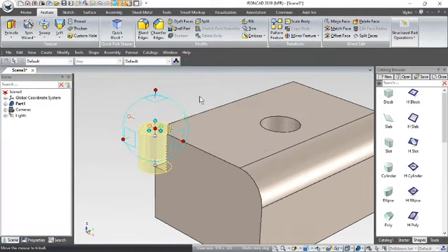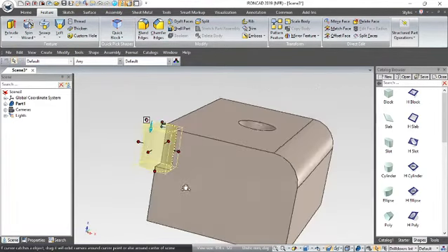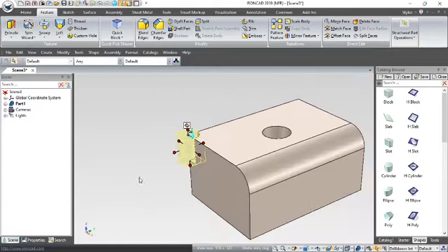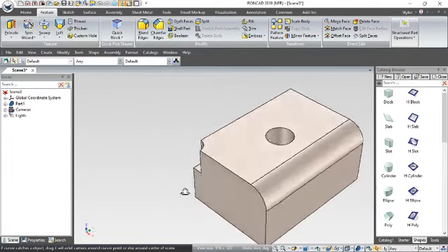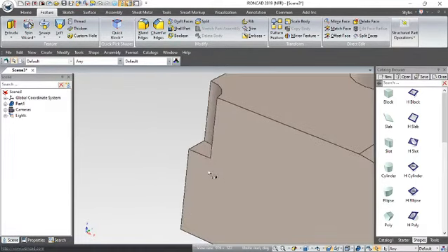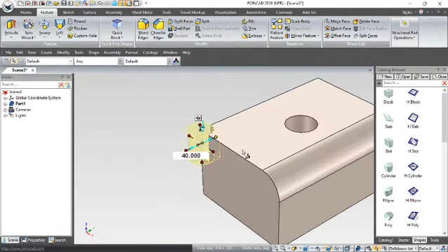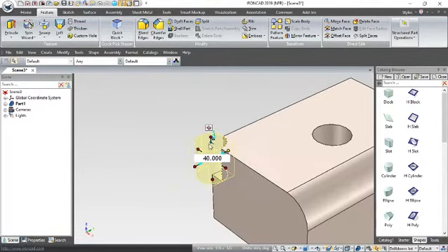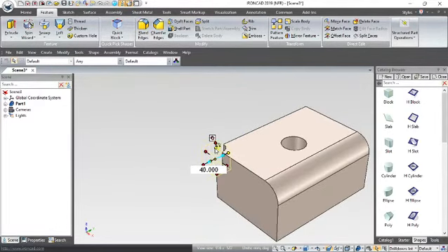So basically now what we've got is our hole, rotated 90 degrees, so it's again in the right orientation. Now if I double click on this hole like so, I can reposition this manually if I wish, and I can use the left mouse button to pick the anchor at the actual top of that cylinder, and I'll just drag it.